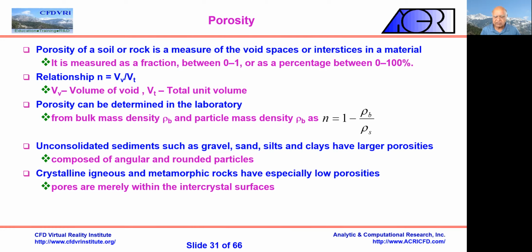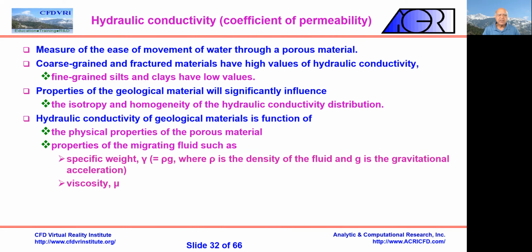Basalt will have a lot of cracks and will not be that watertight. Granite may be more so if it is not fractured. The other concept is hydraulic conductivity, or coefficient of permeability. It's the ease of movement of water through the porous media, okay. The coarse-grained and fractured material will have high hydraulic conductivity, and silts and clays, which are very tight, would have low values, okay.